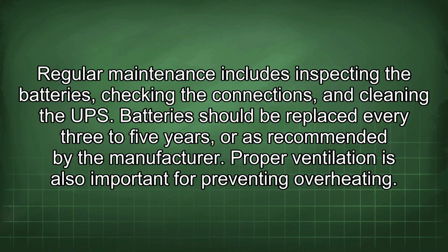Regular maintenance includes inspecting the batteries, checking the connections, and cleaning the UPS. Batteries should be replaced every 3 to 5 years, or as recommended by the manufacturer. Proper ventilation is also important for preventing overheating.